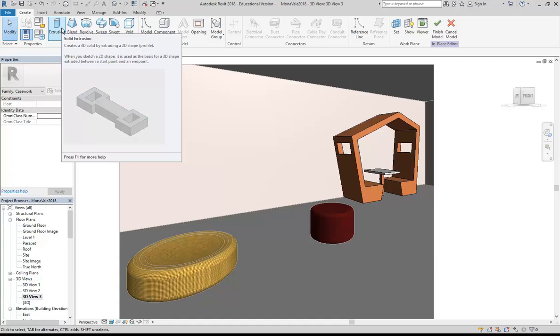There are more advanced modelling tools, much more advanced than this, and you can make anything that you can think of, but you can't always get those things to be built. They don't follow the same manufacturing process. It was interesting. We had a guy, he's actually a pretty good designer, but he's in final year now, and he wanted to do all these really complex curves in his flooring. It should have been simple, but he'd used splines to create the curves. Builders can't make splines. So there's no way they could have cut those patterns, even just to set down on the floor. It's virtually impossible.